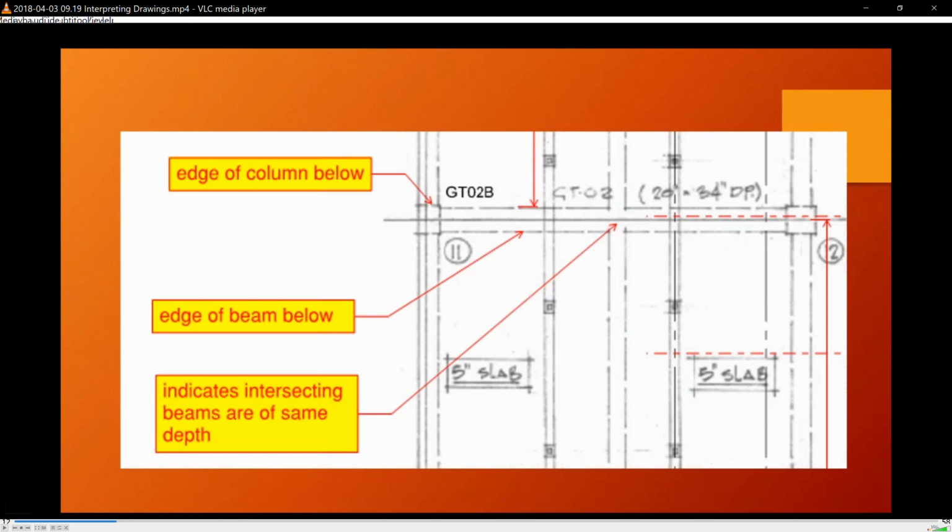The idea when you're looking at a plan view of this floor is that the picture you're looking at is taken like 1 inch above the floor. So it's like a cross section cut right here. And the dashed line with the break in it means that it's happening below. You can't really see it, but it's there.